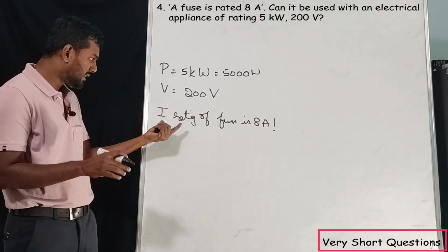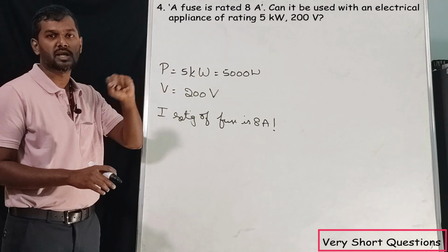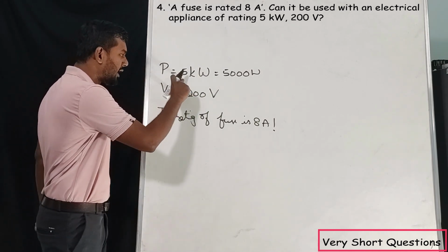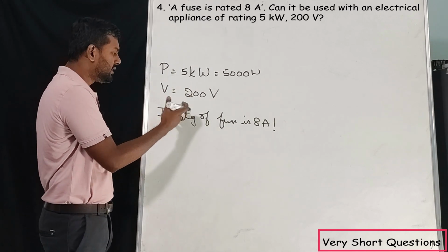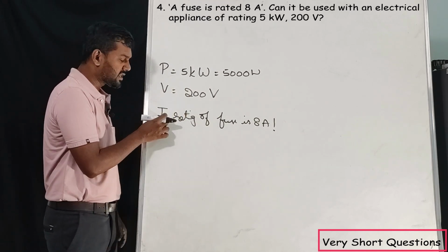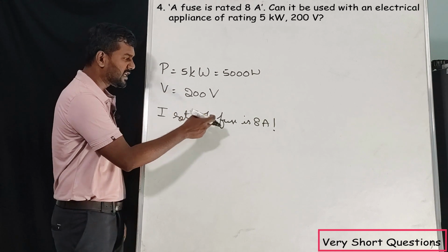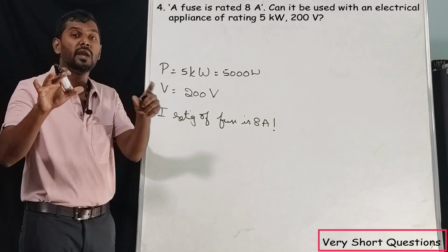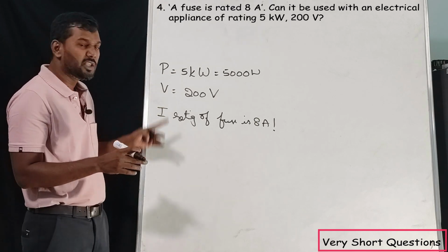So they are asking, can this fuse be used in this circuit? In this circuit we don't know the current, correct? If we can calculate the current, then we can say whether this kind of fuse, the fuse which has a rating of 8 amperes, can be used in this circuit or not.